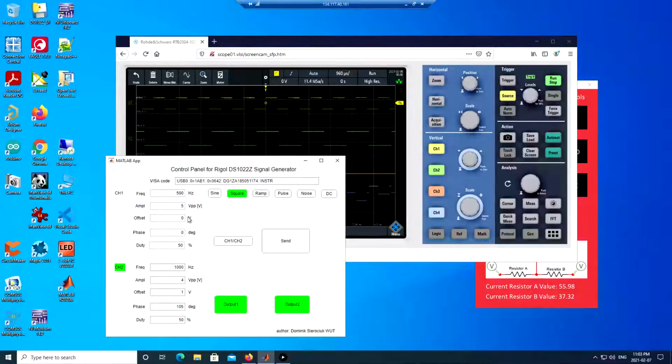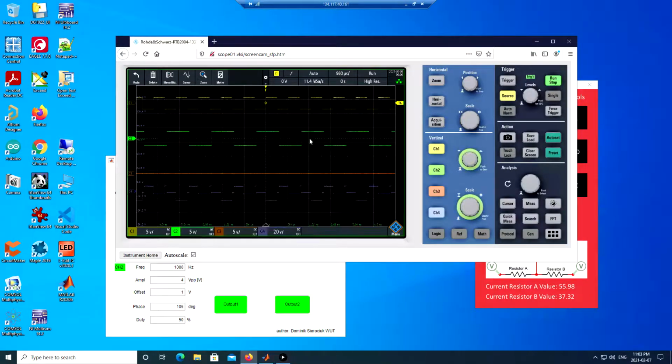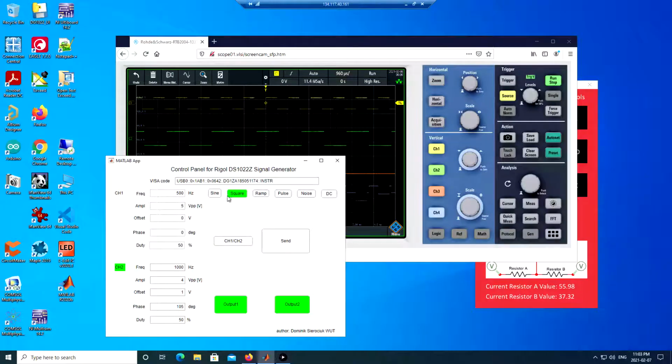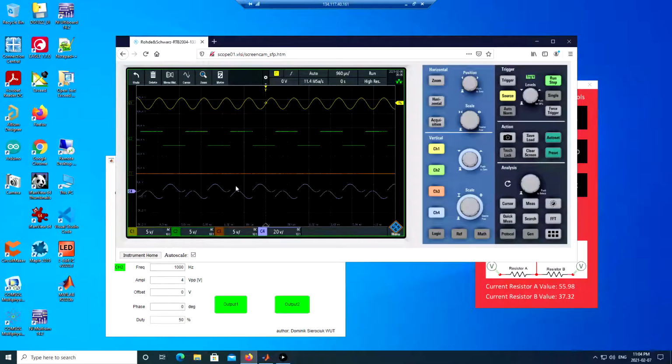So we'll go ahead back to the function generator here. And first of all, we can use either channel 1 or channel 2 to control our output waveform, which is on channel 4. Right, so let's start with channel 2 and we'll make that one the sine wave. Okay, let's start with a 0 degree phase offset, a 0 degree DC offset, and hit send. So we can see our wave is automatically changed.